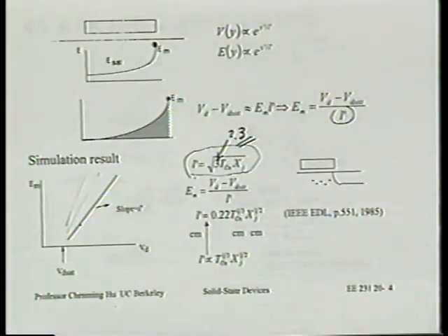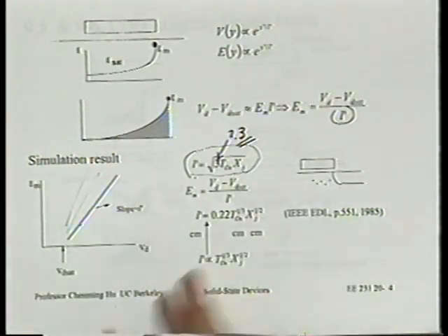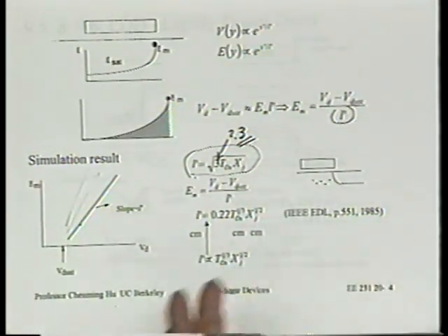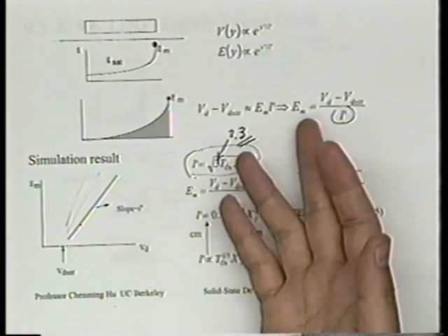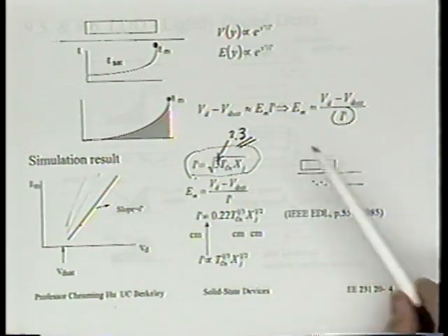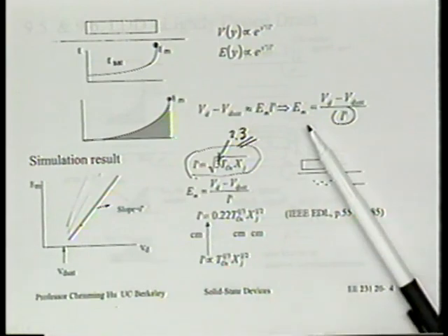So that's electric field. Now, suppose your concern is the electric field is too high, right? You plug this number in, you find out it's larger than the 4 times 10 to the 5th volt per centimeter that I mentioned in the previous slide as being too high, or simply just by experiment, this particular design is giving you a lot of problems with the high electric field.